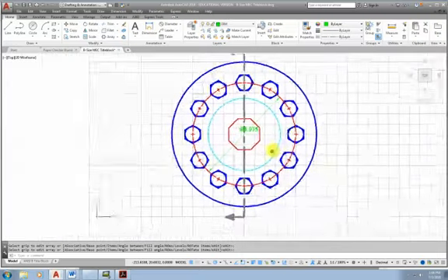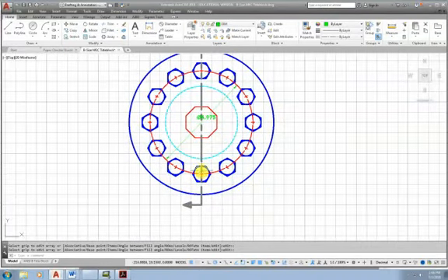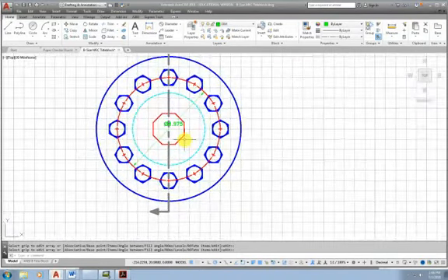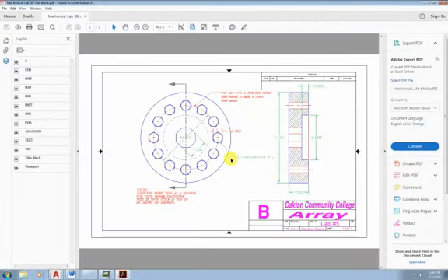And then lastly, we'll put in the dimension for the bolt size, half-20 UNC-2A, meaning it's a half-inch diameter, 20 unified national coarse threads, 2A means that it's an external thread, and the 2 means that it's going to be a 2-inch length.